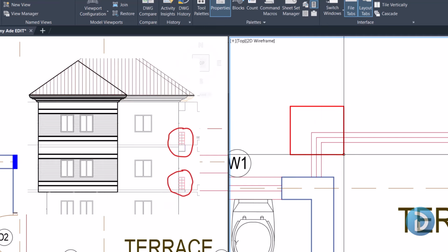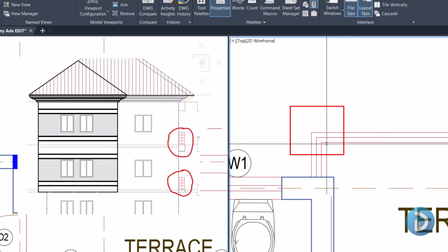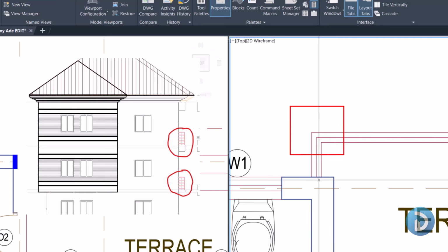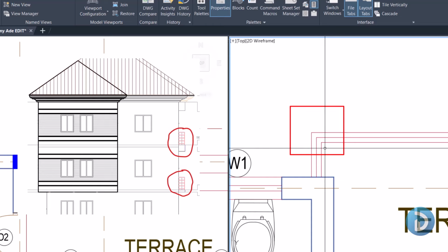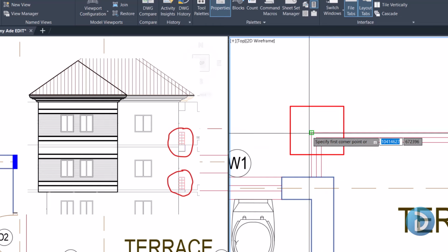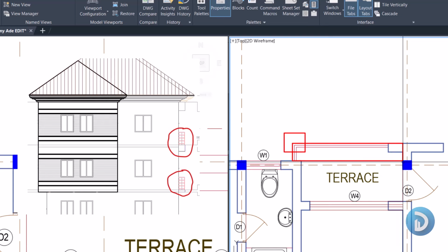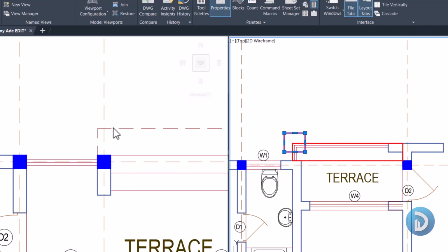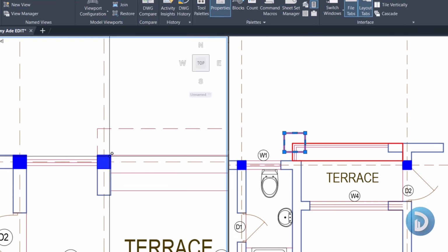By the indication we have over here, it means we cannot put columns at this very position. This is just a handrail, so this will only receive something like a slab, and the handrail will be constructed from here to this part. So this tells us that there is no consideration for inserting a column at this edge. So what will carry this part of the slab will be this